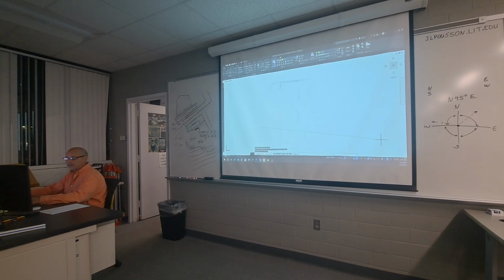410.65 feet. Is less than, so the formula: at, the distance, is less than, the angle. I did the at symbol. Students frequently forget that. I did my distance, and I put the foot mark on there. Students frequently forget that. And then the next thing in the formula is the less than symbol. Same key as the comma key, I just hold the shift key down.